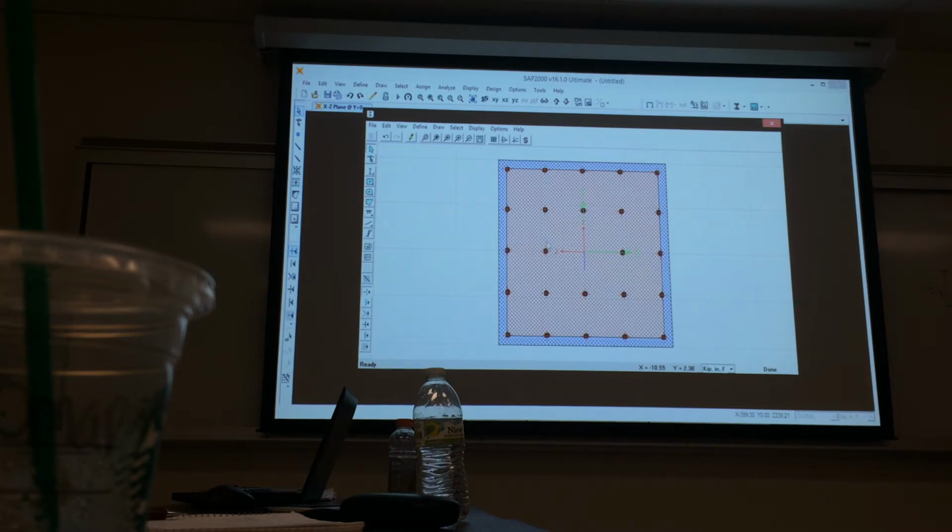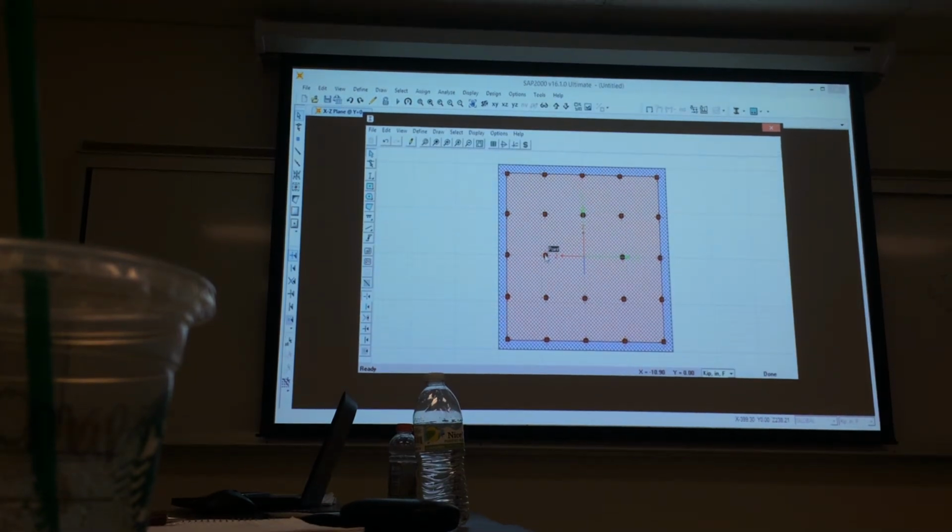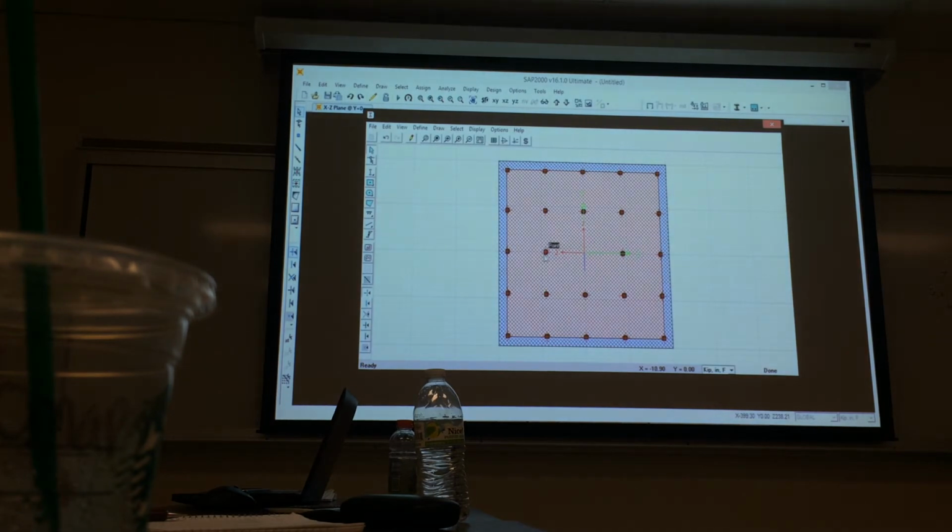Now if you hover over each of these rebars, you'll see the center, the X point down here is now 10.9. So it just takes a little bit of playing around to figure out whether it's going to center lines or to outer edges or whatnot. I think it's going to outer edges instead of center lines, so that's why you go, let's say 23.2 instead of, or 21.8. So now we've got the rebar in our section well defined.